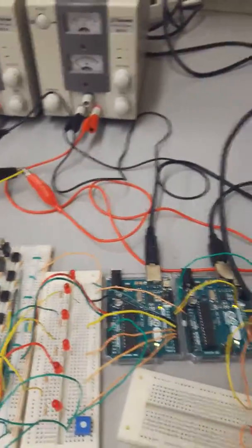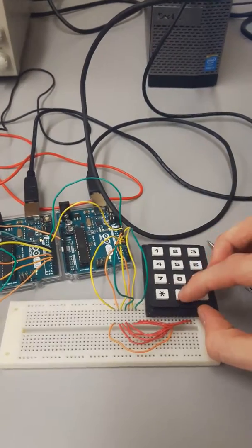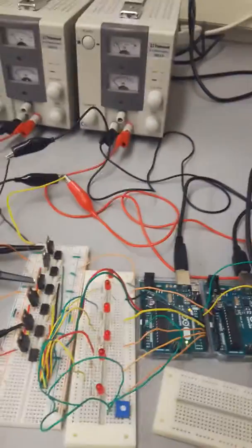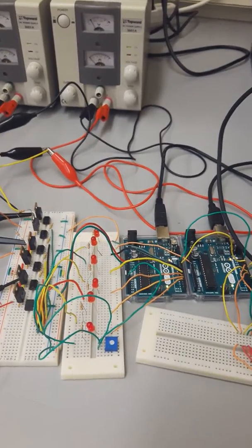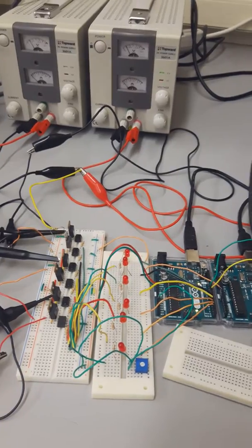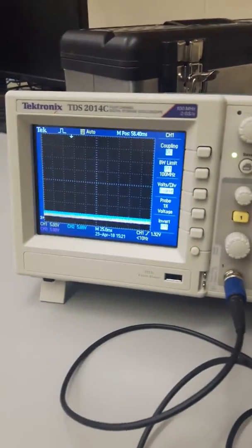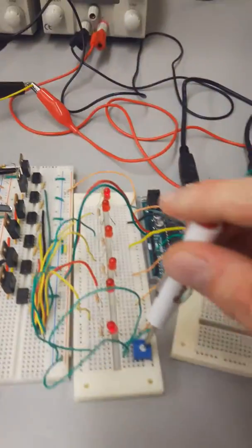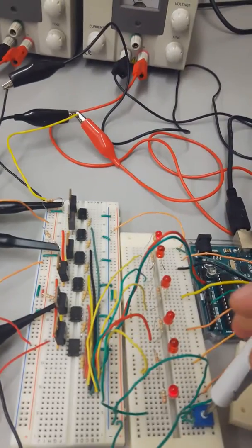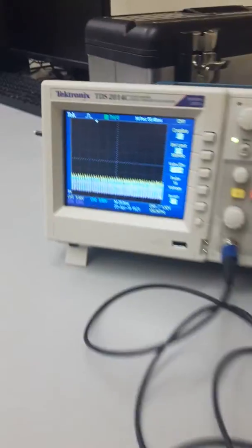Now, problems start happening when we go and increase the frequency up to 60 hertz. The Arduino is not fast enough to run through the lines of code before we require other steps to operate. So we will see different operations. As you can see, it's immediately faulting, but the steps are occurring in the program at its own time.